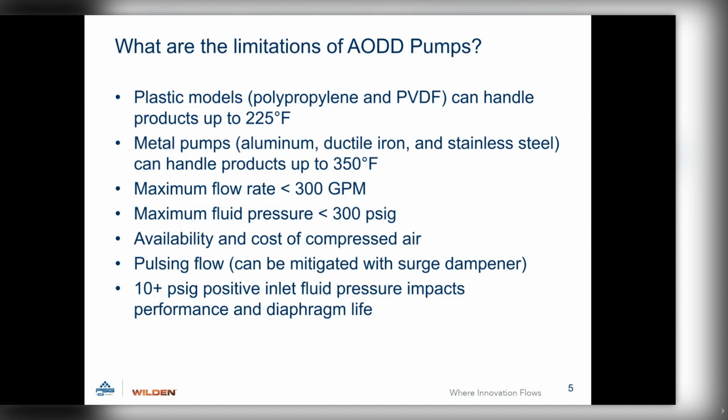Maximum flow rates, we can get up to 300 gallons. So anything over 300 gallons, you'd have to look into another pump technology. And as far as maximum fluid pressure, we can handle pressures up to 300 psi with our high pressure series.